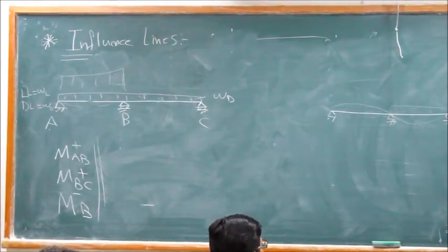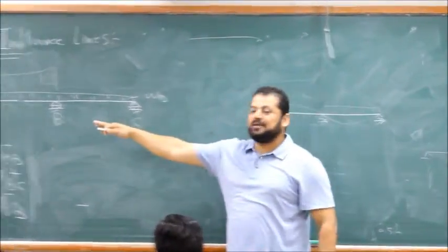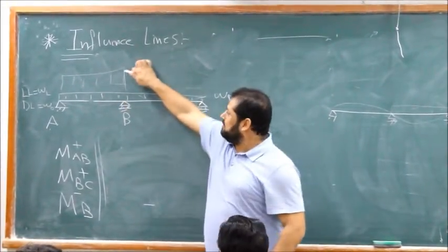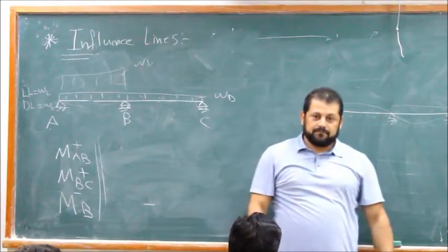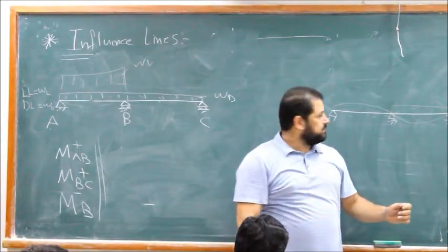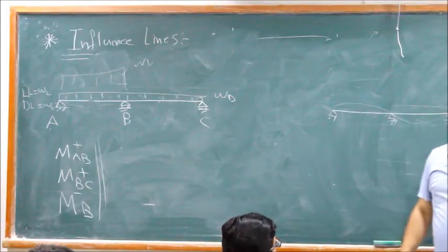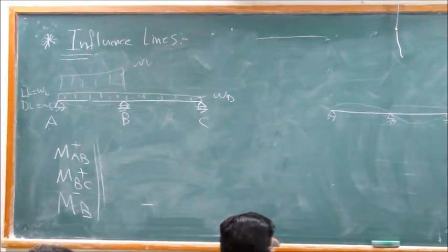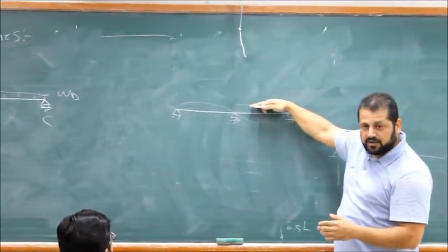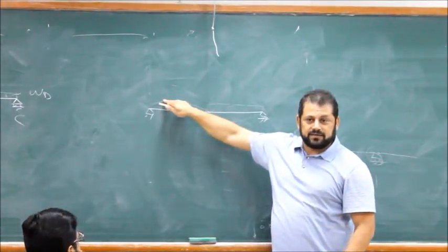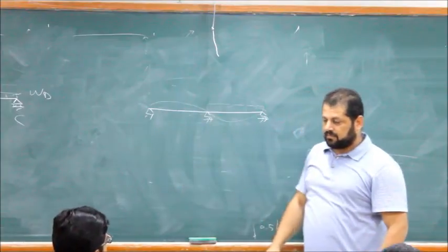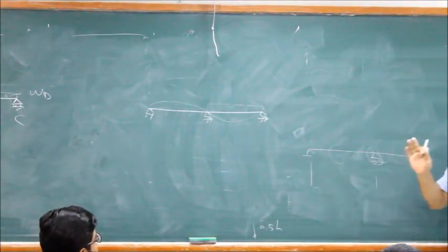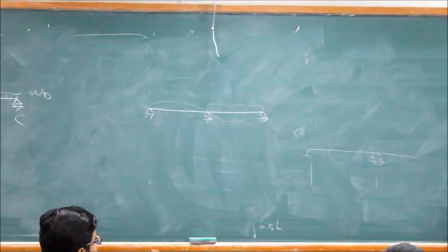And in the case you need to solve it, to find MAB max, this is the case, this is the live load. But if the live load is put on all of them, how will the deflection be? It will decrease, regardless. But you know this live load here will cause negative moment here. So what do you want to do? Put the live load on the first span, or the second, or both?